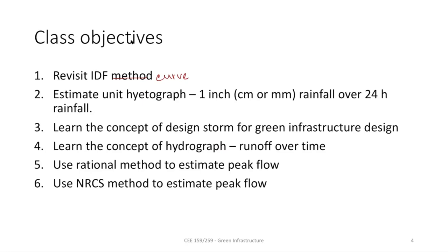As I said, green infrastructure is designed based on a specific rainfall assumption. For instance, for Los Angeles, we say 85th percentile rainfall. You learned that. What does that mean? It means that of all the rainfall received historically in this area, 85% of the rainfall will be captured in this green infrastructure design. Anything beyond that would be too expensive to build because those are heavy intensity rainfalls.